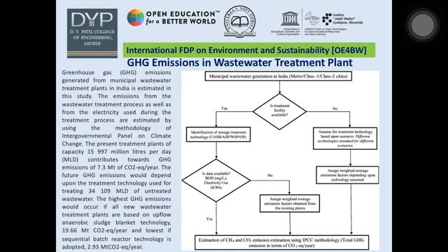If no, then what you have to do? Then you have to assign weighted average emission factors obtained from the existing plants. If the treatment facility is not available, what do you have to do? Assume the treatment technology based upon scenarios. Different technologies are assumed for different scenarios. Assign weighted average emission factors depending upon technology, and then estimate the greenhouse gas emissions.